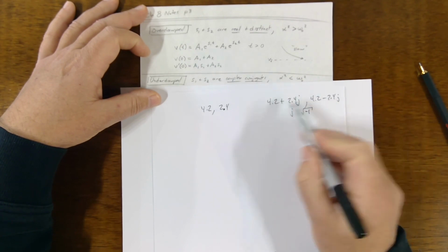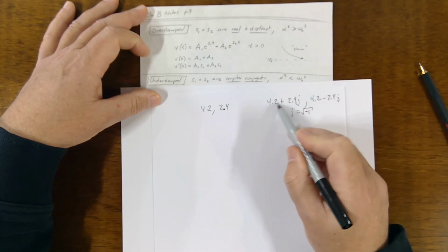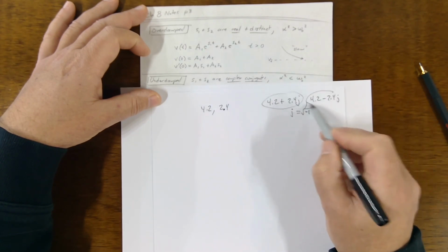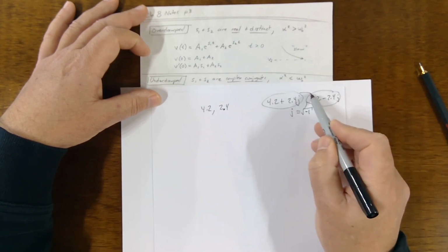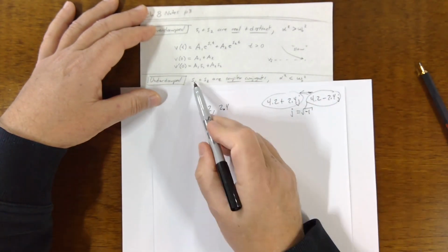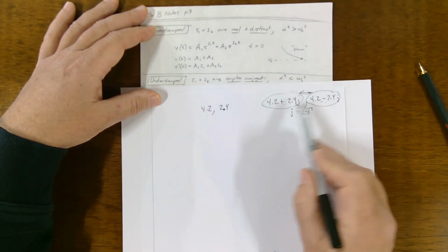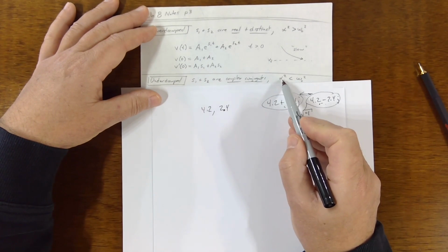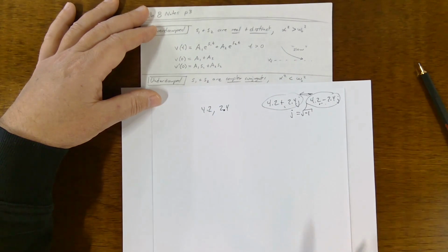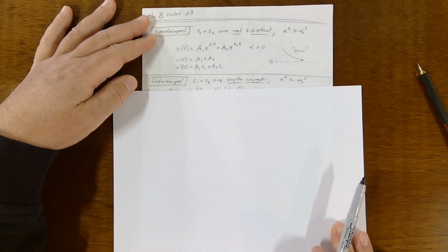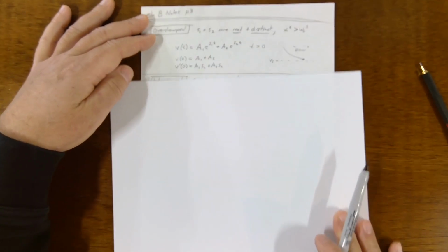Anyway, each one of these is a complex number, right? It has a real part and a complex part. And this whole thing is a complex number, and this whole thing is a complex number. These two numbers are complex conjugates because they differ only in their sign, all right? So if S1 and S2 are numbers of this form, then it's underdamped. And it will also be true that the magnitude of alpha squared will be less than omega 0 squared. So if that's the case, then this thing is underdamped, and our general solution